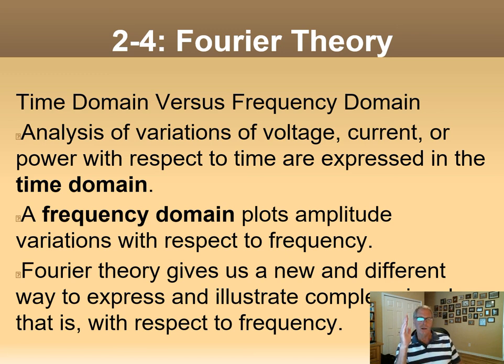Let's say it's a 100 kilohertz square wave, you're going to see 100 kilohertz, 300 kilohertz, 500, 700. As you go up into the harmonics, the amplitude of those components reduces. The main bang of the fundamental, 100 kilohertz in my example, is going to be the highest amplitude. Then as you go to 3, 5, 7, they get smaller and smaller.